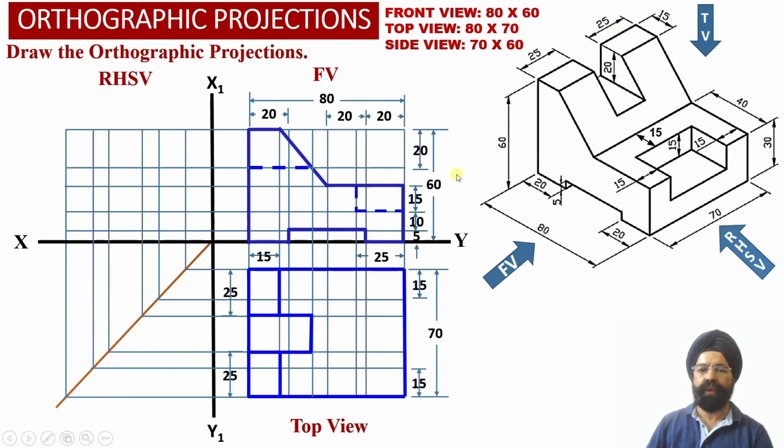So one rectangular surface is available towards the rear face of the solid. Another rectangular surface is available towards the front face of the solid. The true shape corresponding to these top rectangular surfaces is visible to the observer from the top view orientation. Why? Because these 2 rectangular surfaces at the top happen to be parallel to the horizontal plane.